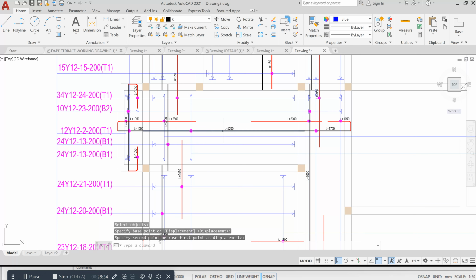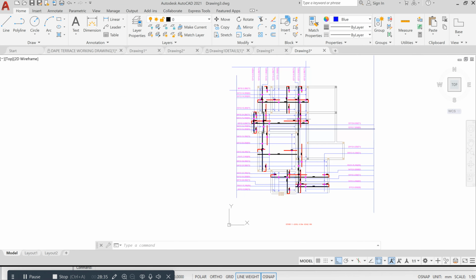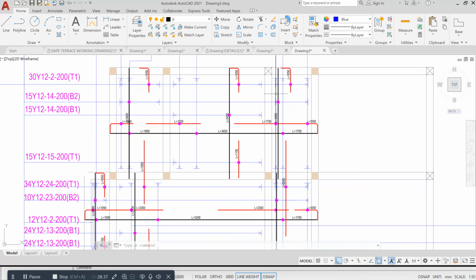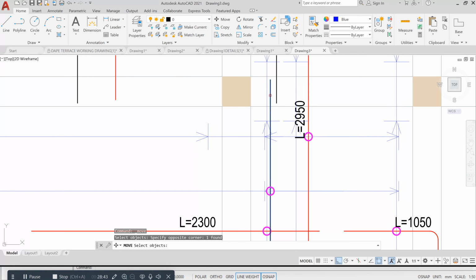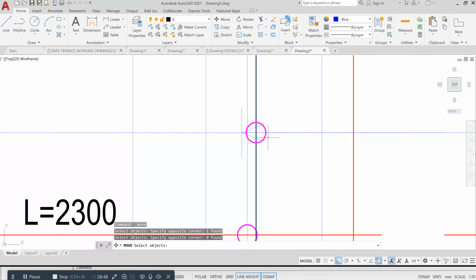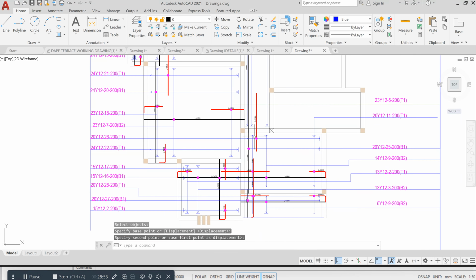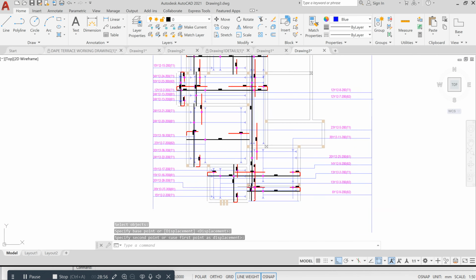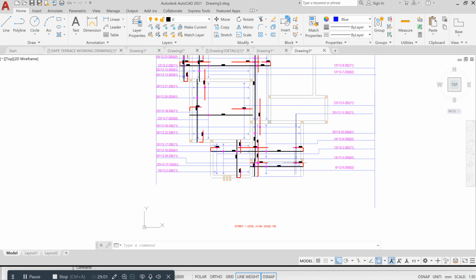So I'm going to measure this. Okay, this is 5 meters, this is 6, this is about 9 meters. So okay, a full length can actually cover here. For where you have a length more than 12 meters, your reinforcements are not supposed to be joined together. So I can work on this, join it here. Okay, then I will have a cutting here, and this is okay.